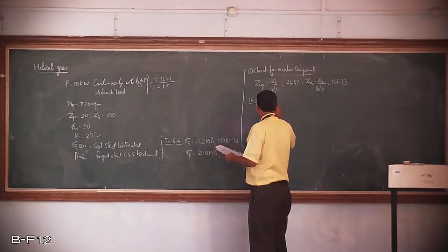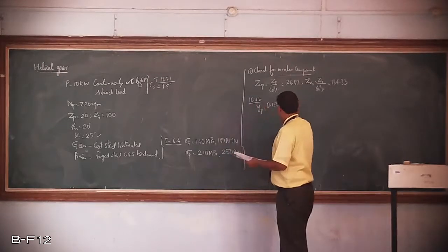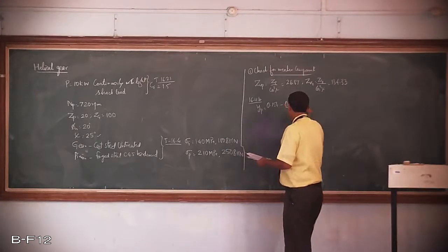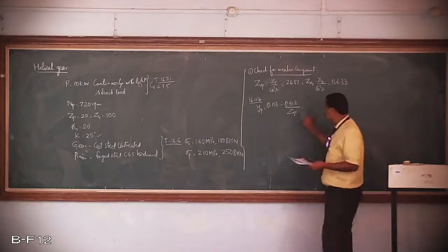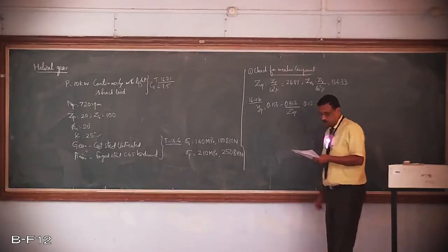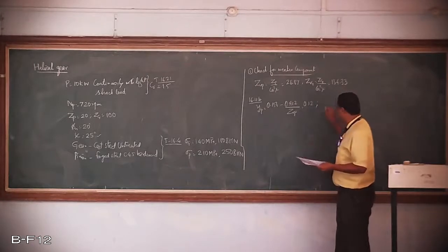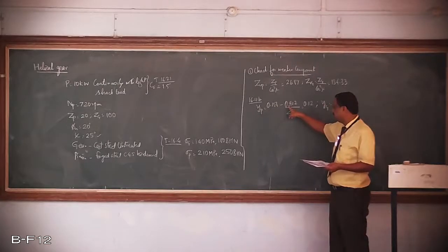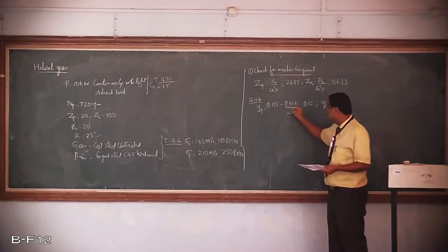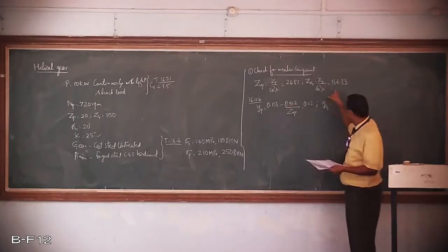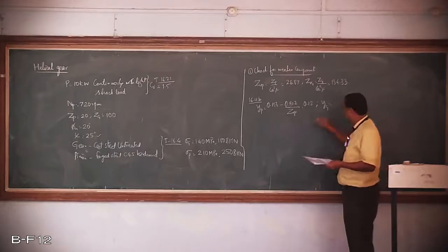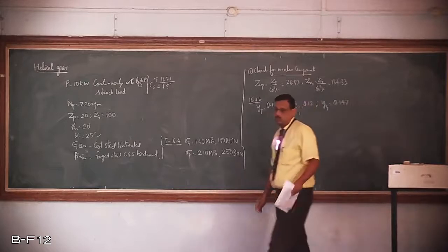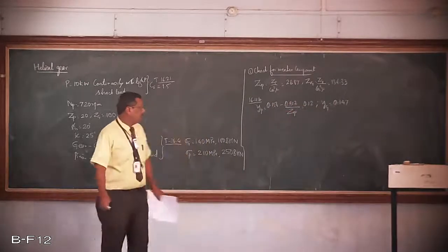It is 0.154 minus 0.912 divided by z, where instead of z we have to write the virtual number of teeth, not zp. For the pinion it is 0.12. Similarly, for the gear, y is 0.154 minus 0.912 divided by ZVG, where ZVG is 134.33. You get 0.147. Therefore, we have calculated both values of the Lewis form factor, Yp and Yg.